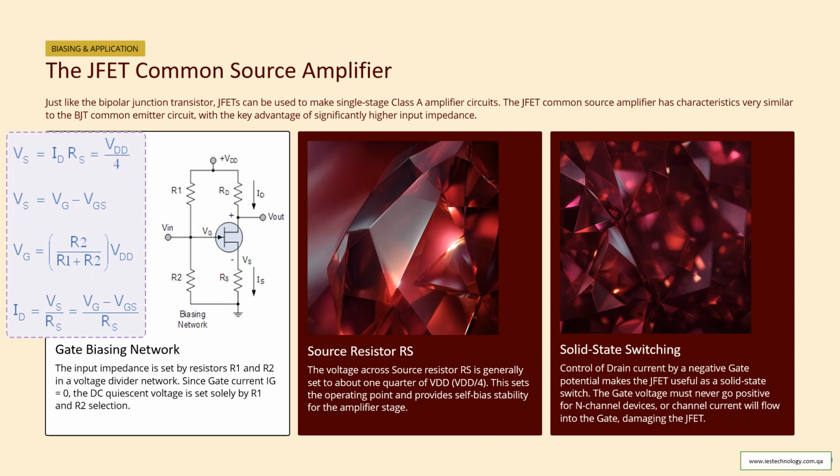Solid-state switching. Control of drain current by a negative gate potential makes the JFET useful as a solid-state switch. The gate voltage must never go positive for N-channel devices, or channel current will flow into the gate, damaging the JFET.